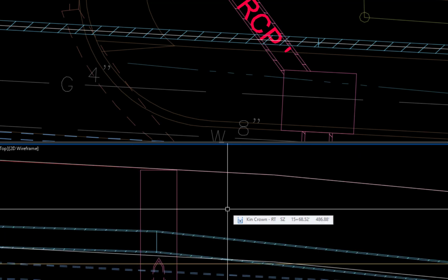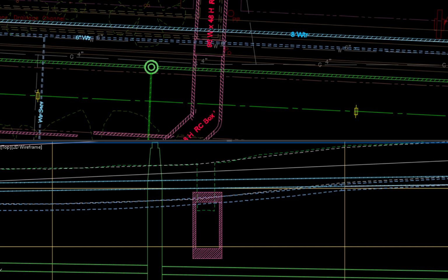The water pipe will have a depth of cover of slightly less than 2 feet, which is below the 18-inch frost line depth. There is a potential conflict where the water pipe crosses the 96 by 48 RC box around 26+50 in Kincaid. The water pipe is currently slightly above the RC box, which is okay, and has a slope of 0.36%.